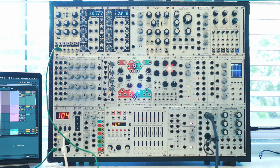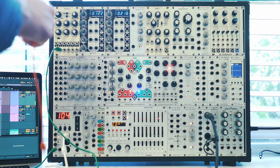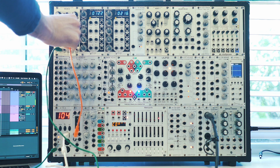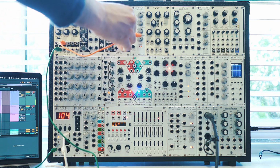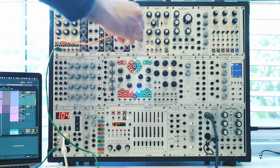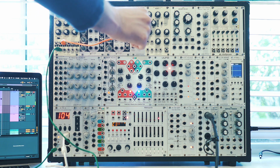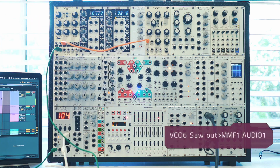All right, now the VCO-6 has a bunch of waveform outputs. They're all labeled with the black background. So I'm going to take the third output here, which is a sawtooth, and I'm going to plug that into the filter, the multi-mode filter, MMF-1. It has two inputs, audio 1 and audio 2. I'll just plug it into audio 1. There is a level control for audio 1. I'm going to set that in the center.